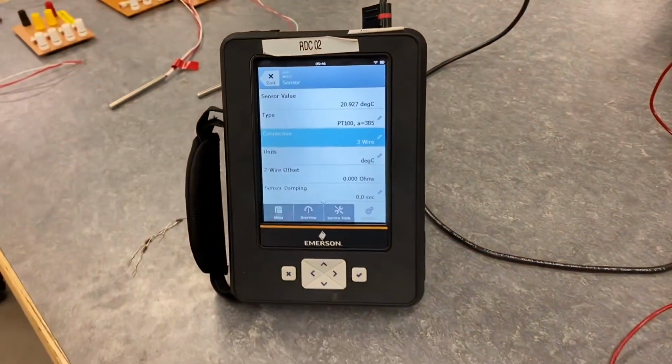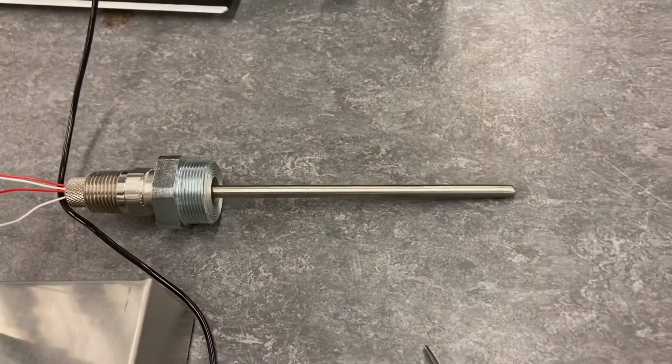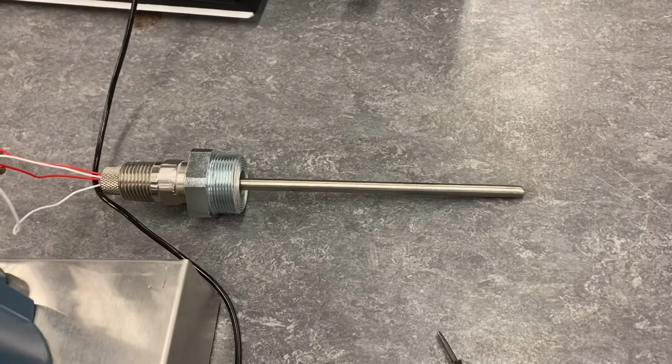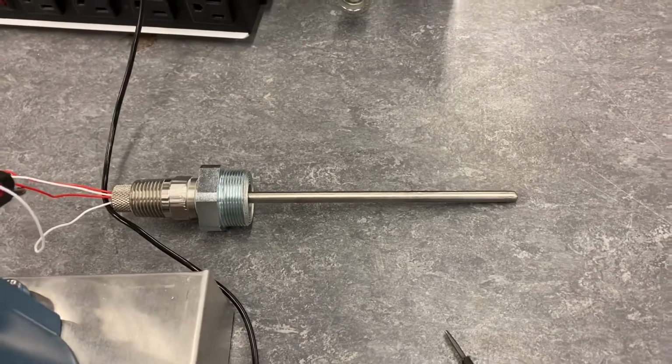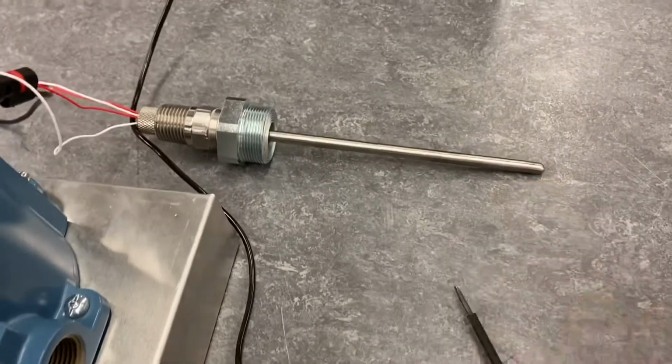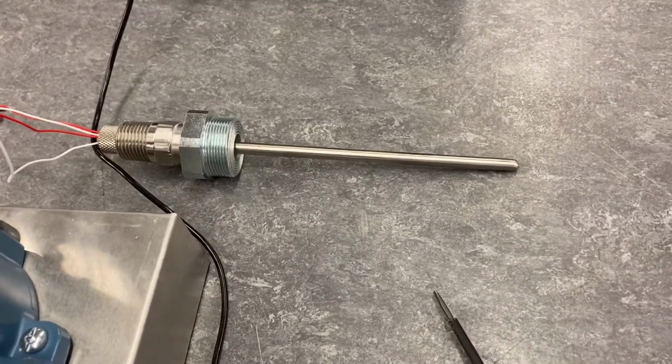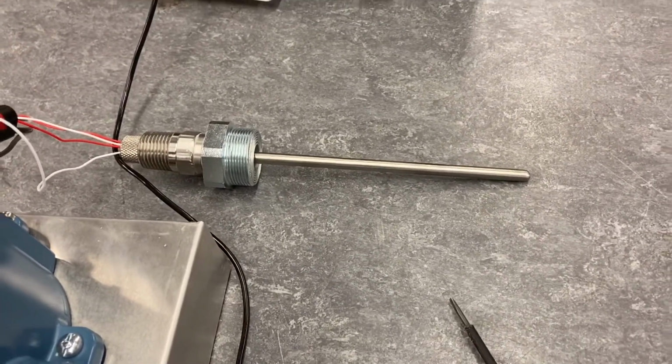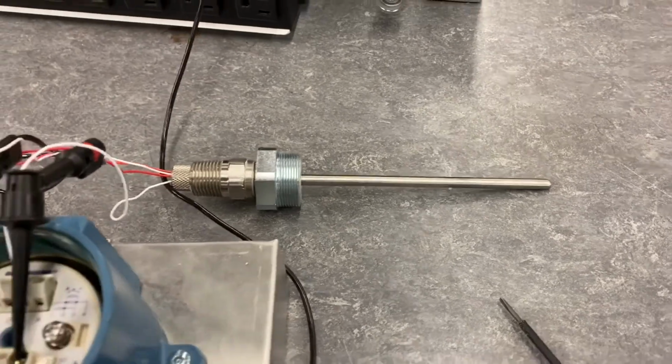Right, so for doing this test, we want to make sure that the temperature of our RTD is stable, that it's cooled down or warmed up to room temperature before doing these. That might take submerging it in some room temperature water to bring it up to temperature and agitating it. It shouldn't take long to bring it up to temperature.